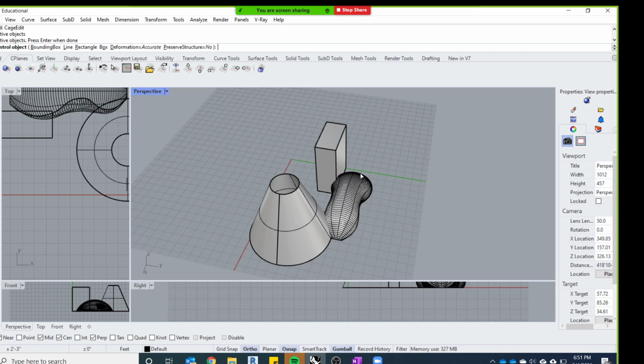Imagine when you're rotating an object, you have a start point, and then you pick that second point, and then you rotate that object. So I'm basically picking my reference point, and I can start to twist this object. Turn off my ortho, as much or as little as I want. When I click the end and I'm done, I now have a twisted cube.